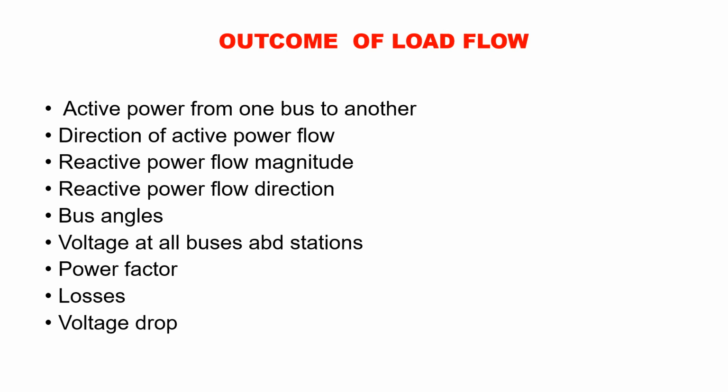Fault is something very different from an intentional outage, switching off a generator, an alternator missing, a transformer missing, out of service, under maintenance. So those are the contingencies. So don't mix up contingency with the fault. Fault means a heavy fault current. That is a different kind of study: the transient state stability and the short circuit study.